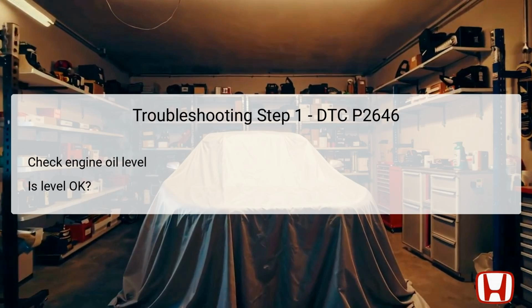Therefore, it's essential to check the dipstick to confirm whether the oil level is within the recommended range specified by the manufacturer. Should the oil level be low, topping it up to the correct level is necessary before proceeding. If the oil level checks out, the investigation transitions to other components and systems. This initial verification is pivotal, as addressing simple oil level deficiencies can often resolve performance concerns without needing more complex